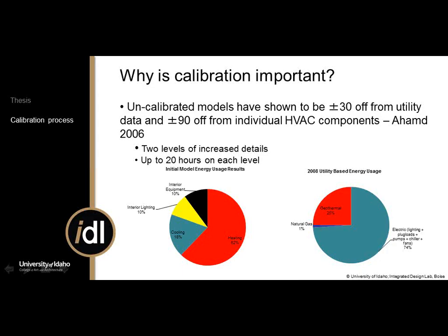They took a lot of actual measured utility data from LEED buildings, tried to compare them against the energy models, and they tried to raise this idea that, oh, well, it's not actually consuming as much energy as you predicted in your model. But you can't really compare the two because the ASHRAE Appendix G protocol is not a predictive energy model like energy calibration. So there are two very different animals. So that comparison wasn't necessarily fair for them to be able to make some of those assumptions.